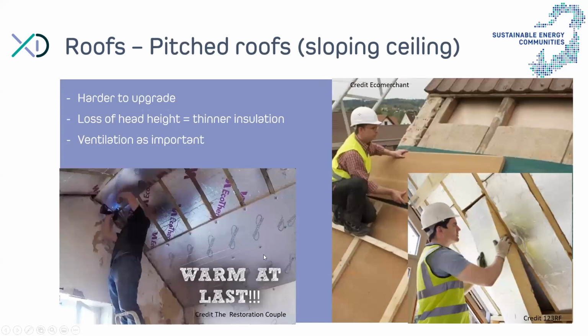I should have mentioned here that any insulation is going to take up headspace essentially within the room underneath. The rigid boards with a high level of insulation per, let's say, an inch of insulation is very helpful in achieving a good level of performance without taking too much space internally.